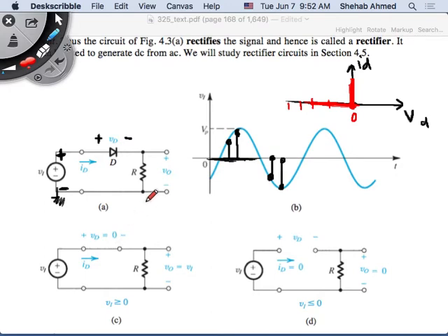But the input voltage has to be greater than, for example, 0.7 practically. If I use that model, but if I use the ideal model, this is my ideal model. The ideal model has, as soon as the voltage is positive, it will conduct. That's why it makes the halfway, because it won't conduct at negative.